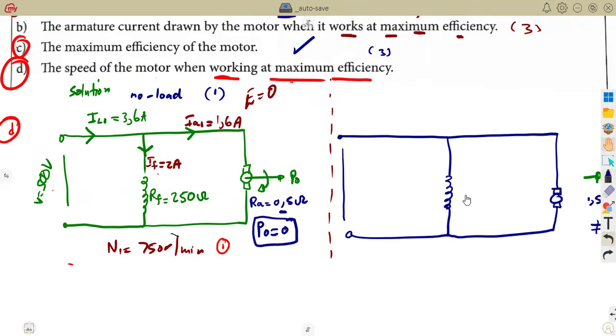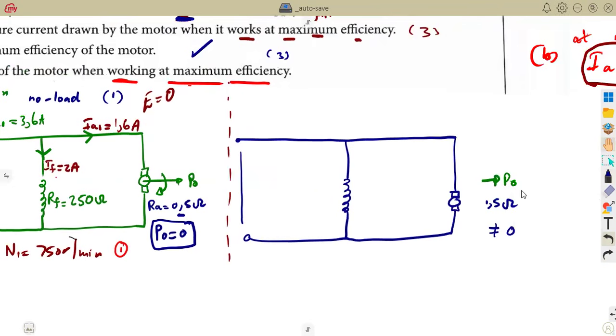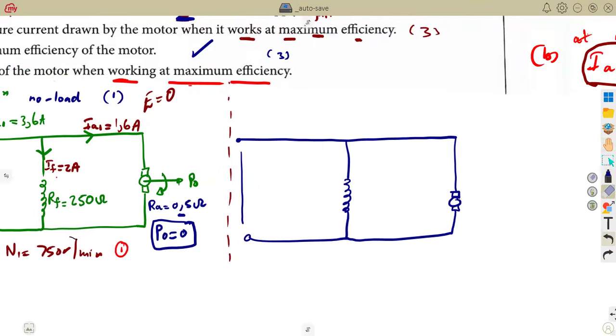We just need that basic view. So here, guys, I'm just going to repeat that diagram the way it was. I hope you're together because the load current, we calculated this one together. This is at maximum efficiency. Remember, it was 61.979 amps entering the field, then the other one going to the armature.